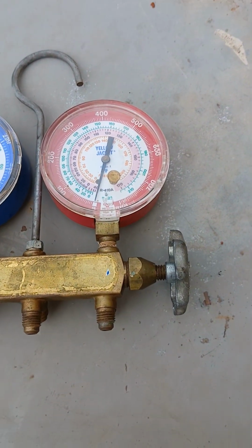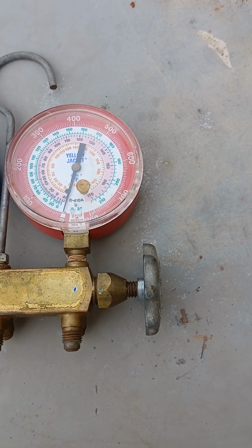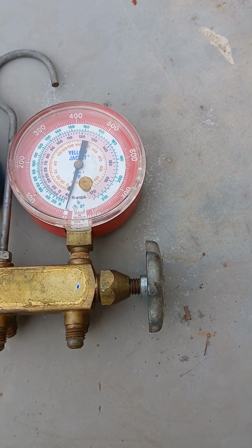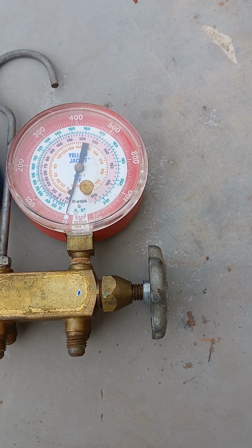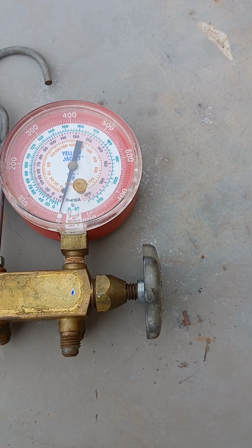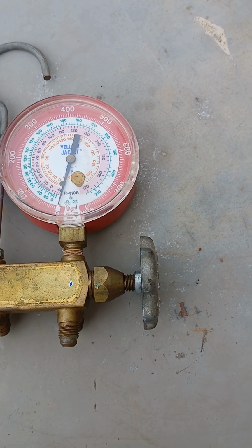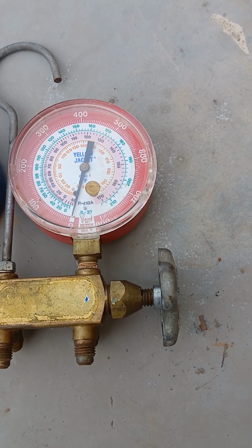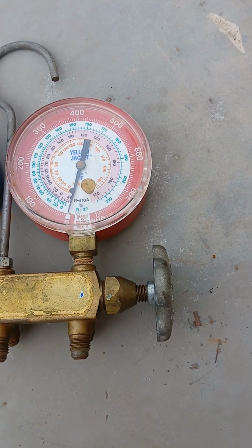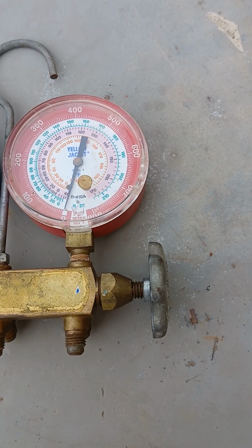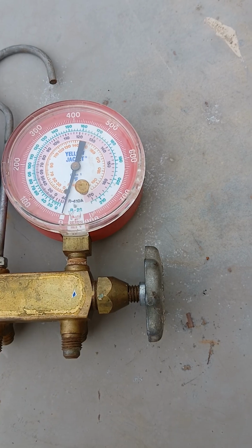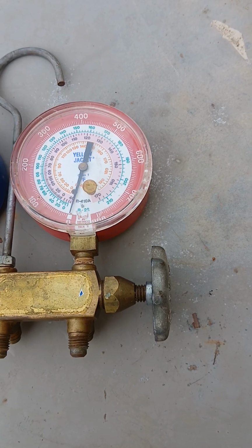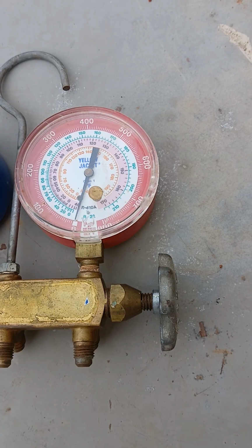Effectively, the refrigerant comes out of the A coil and comes back to the condenser and the compressor, maybe as a low pressure vapor, gets compressed, then turns into a high pressure vapor. Then the air, usually via the fan, comes across.